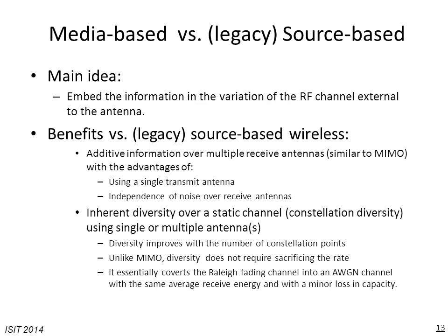Another benefit, I'm now at the second bullet, another major benefit which applies to both single transmit, single receive antenna systems and single transmit, multiple receive antenna systems, is that in media-based modulation we have an inherent diversity over a static channel, which I am calling constellation diversity.